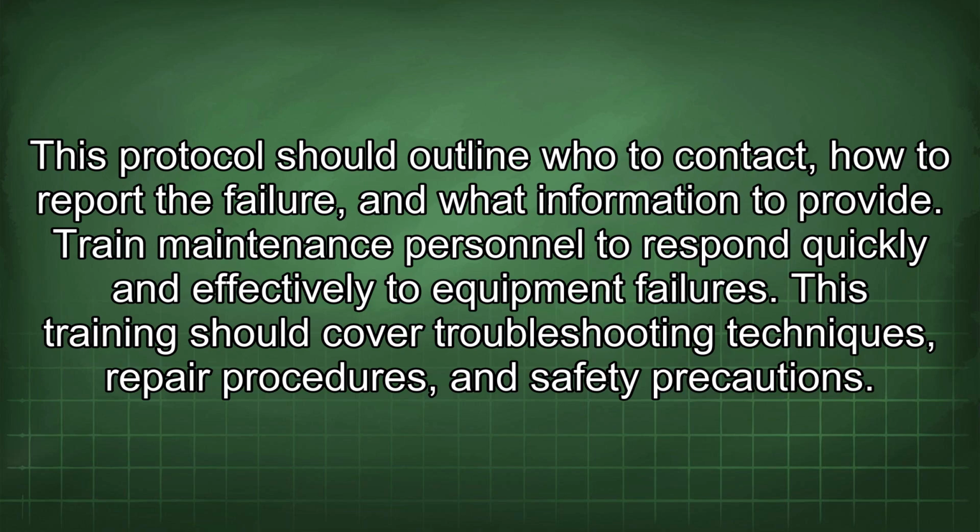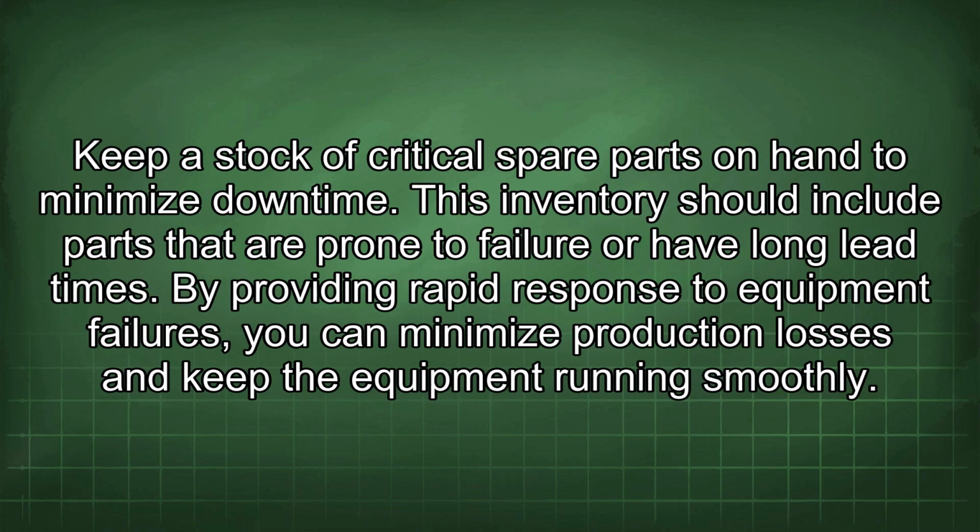This training should cover troubleshooting techniques, repair procedures, and safety precautions. Keep a stock of critical spare parts on hand to minimize downtime. This inventory should include parts that are prone to failure or have long lead times. By providing rapid response to equipment failures, you can minimize production losses and keep the equipment running smoothly.